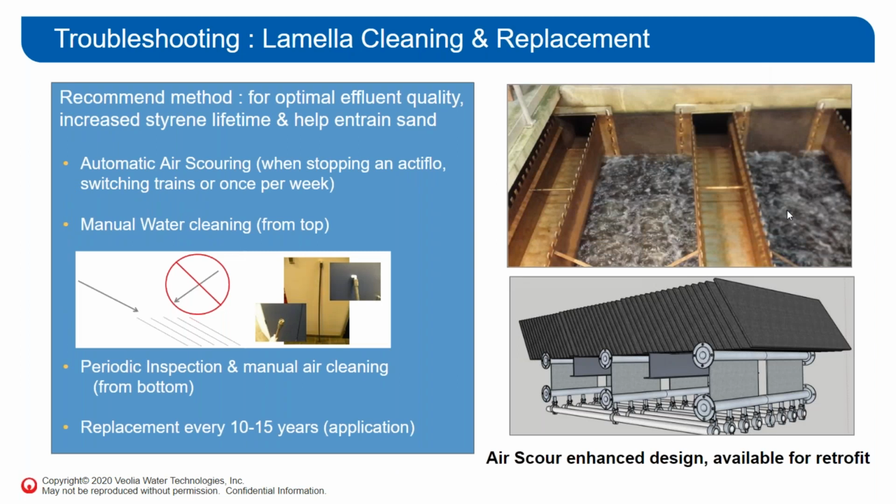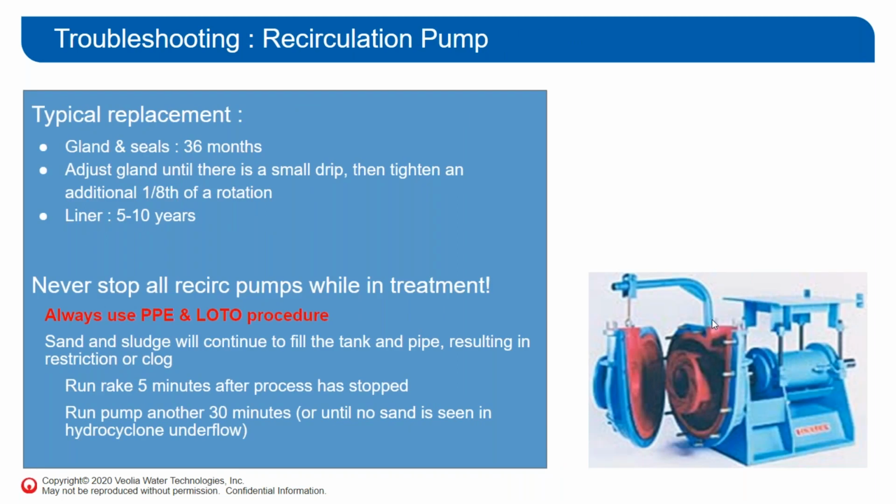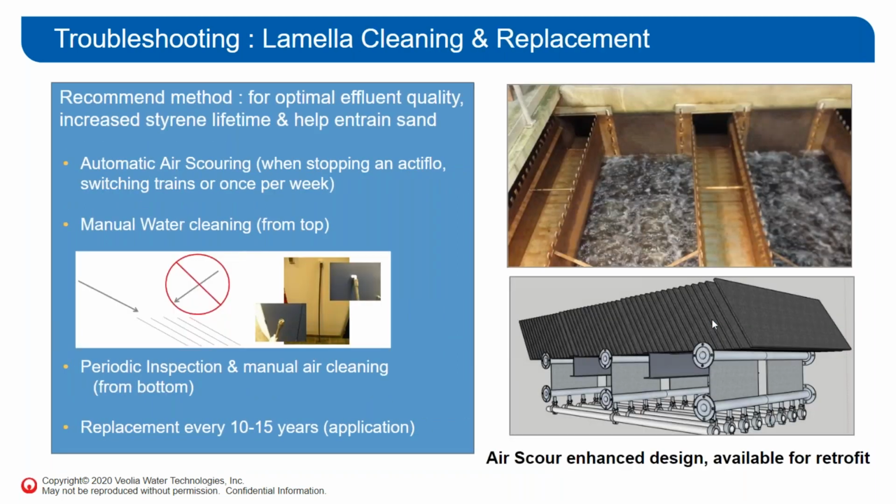So lamella cleaning is, like I mentioned before, whenever this polystyrene catches the solids in the sand that you're settling out time after time, whether you're building a sludge blanket or not, it's important to make sure that it's clean, because even if your process is perfect, just the velocity and the upflow of your water is going to carry out some of that buildup.